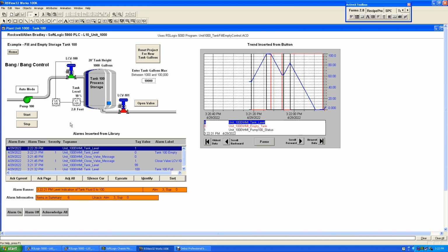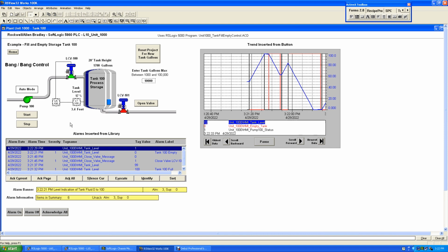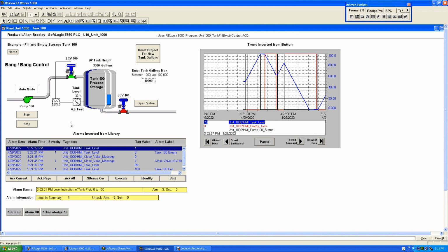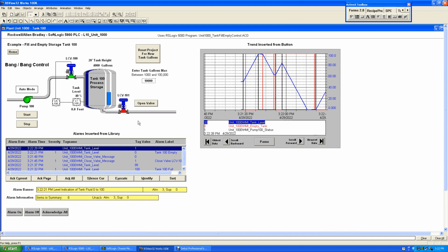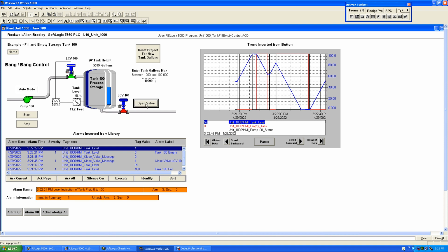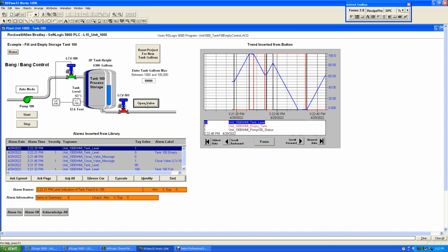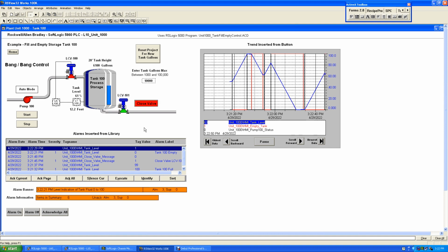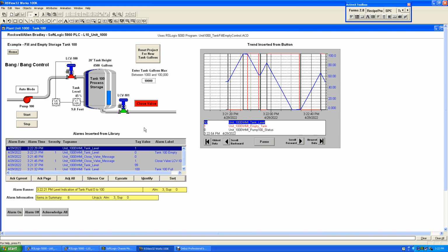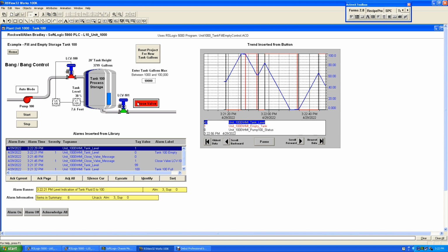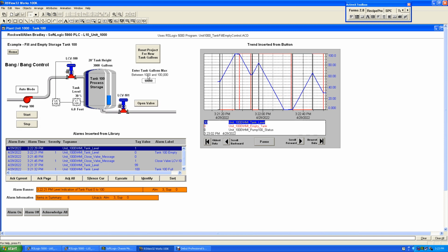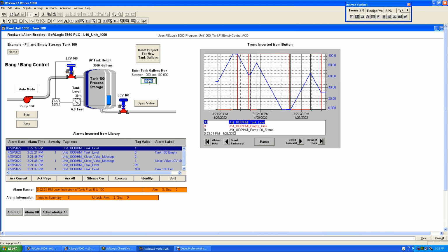And it'll fill again. And you can fill and empty it from any position. So it doesn't have to just fill up all the way and empty all the way. You can do it from anywhere. So it's kind of cool. I did this with timers and scaling the timers, and subtract from the accumulated values of the timers. So as you're timing to empty, the timing that it takes depends on how many gallons you got in there.